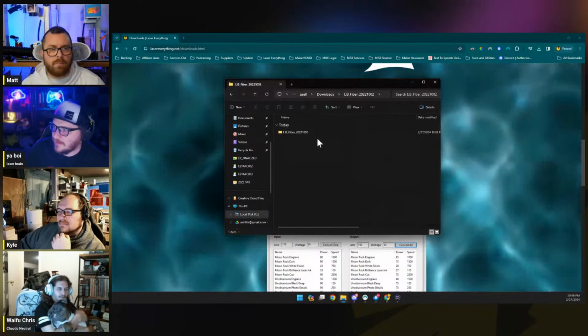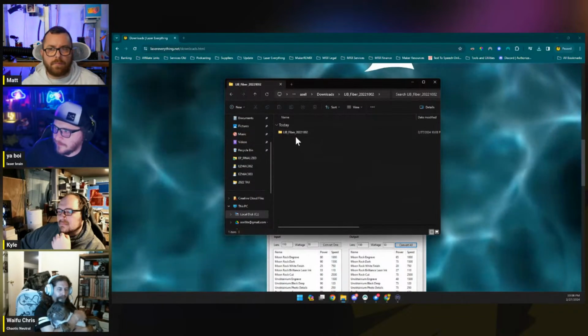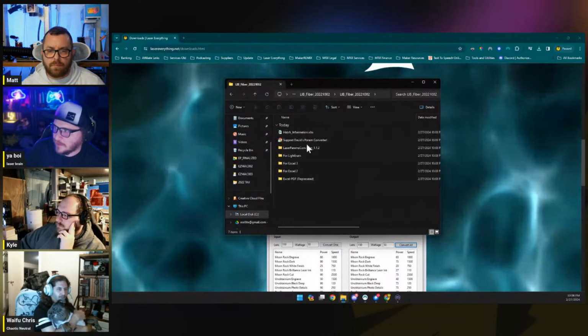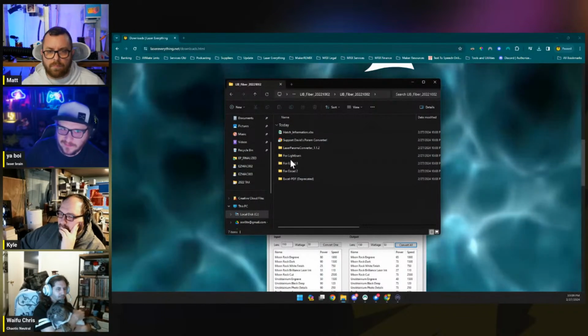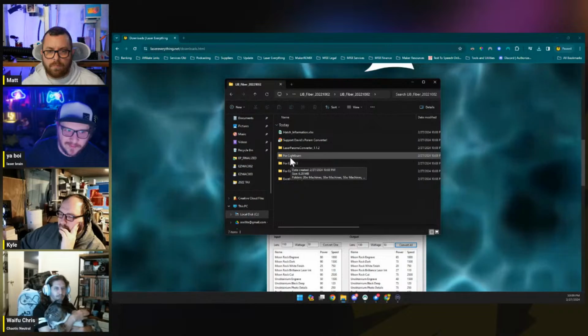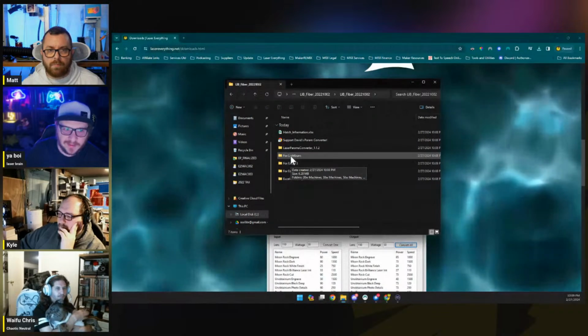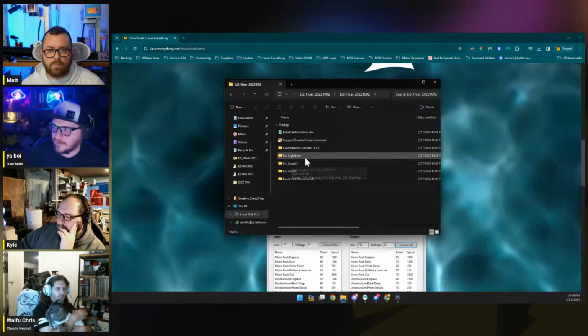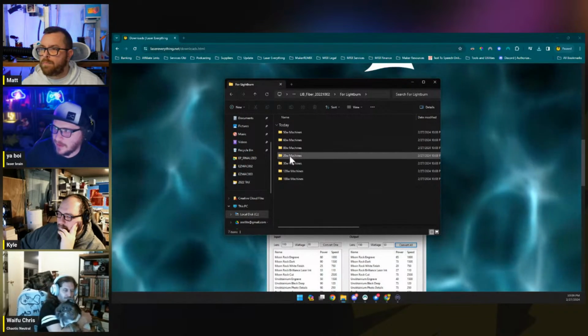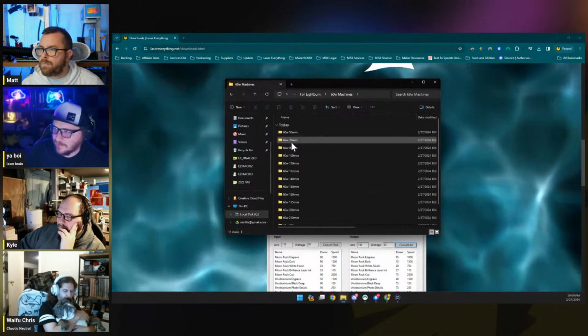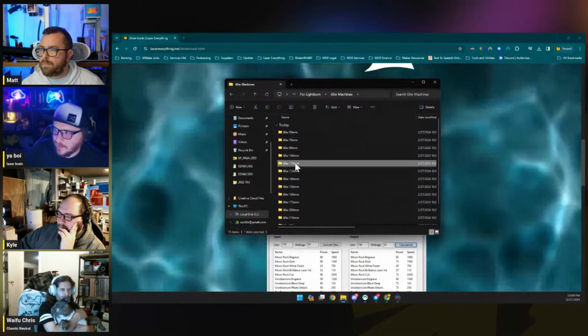And inside this folder, this is what the free parameter libraries look like. You're going to find a bunch of different files. There's dozens and dozens of files here. Kyle spent weeks of his life converting these for every wattage and every lens, so you don't have to. This question is about Lightburn, so we're going to be looking for a Lightburn library. And let's say it's for a 60-watt machine, and they're using a 110 lens.